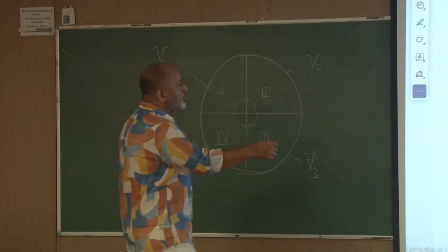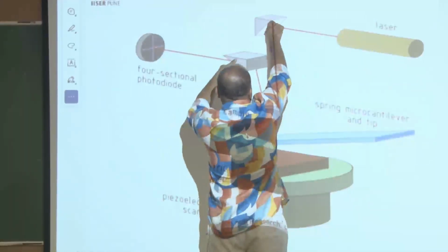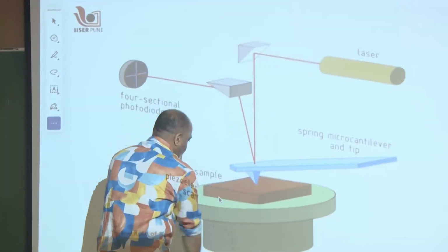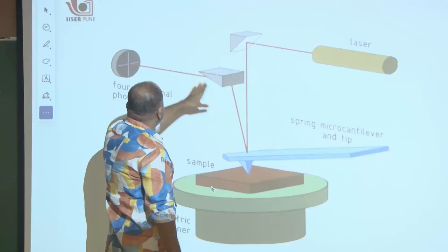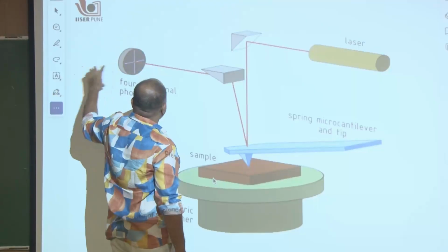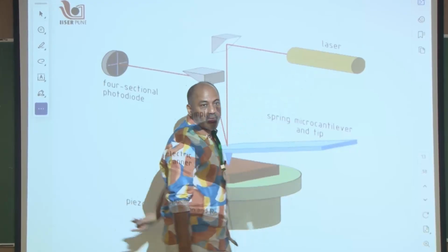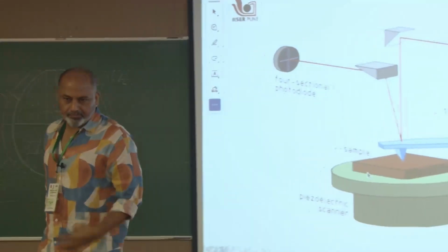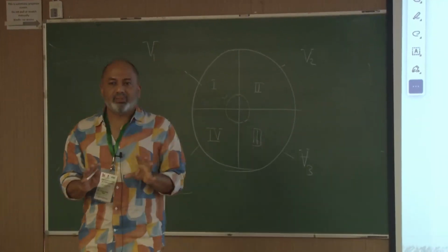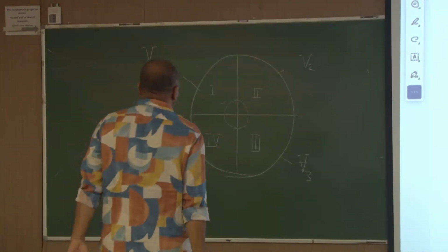So with the help of this laser, which is mounted on a holder with these two mirrors, I can deflect it up and down before anything, the substrate all the way down. If I shine this laser and focus it in the center by moving the detector up and down and sideways, and playing with the mirrors and the laser, that's the alignment procedure. We'll do this today in the lab. Doing all that, you put the light coming from the cantilever in the center, and all differences are 0.